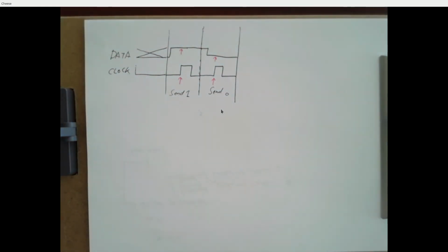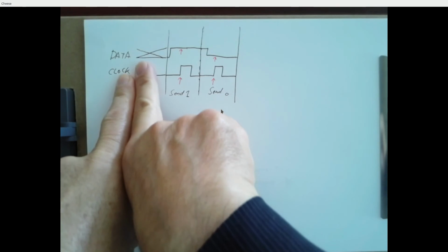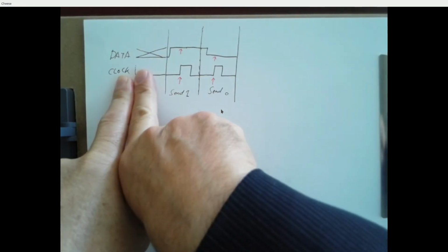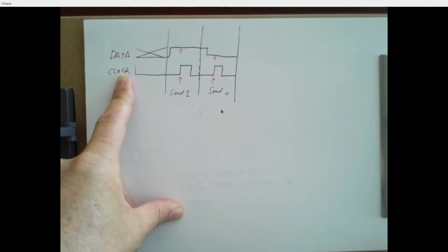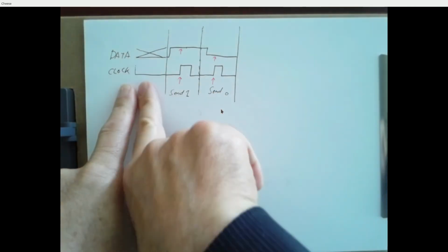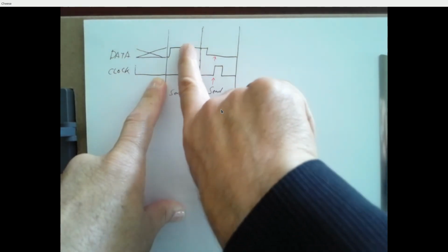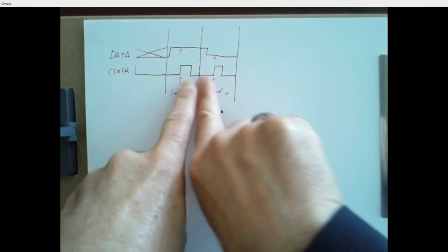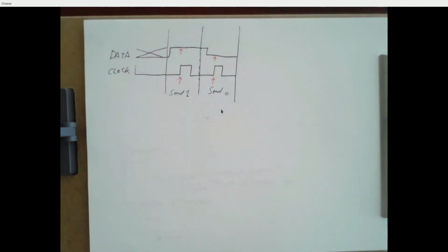So we've got a sender and a receiver. Okay, this is what the sender is doing. They're controlling the data and clock. How do you do that? It's like lighting LEDs. Right? Your LED labs, you learned how to put 5 volts or 0 volts on a pin, so that's what you do with these 2 pins. Set this pin to 0. If you want to write a 1, set that pin to a 1, then set the clock to 1, then set it to 0. On the receive side, you know how to read the voltage level on a pin.